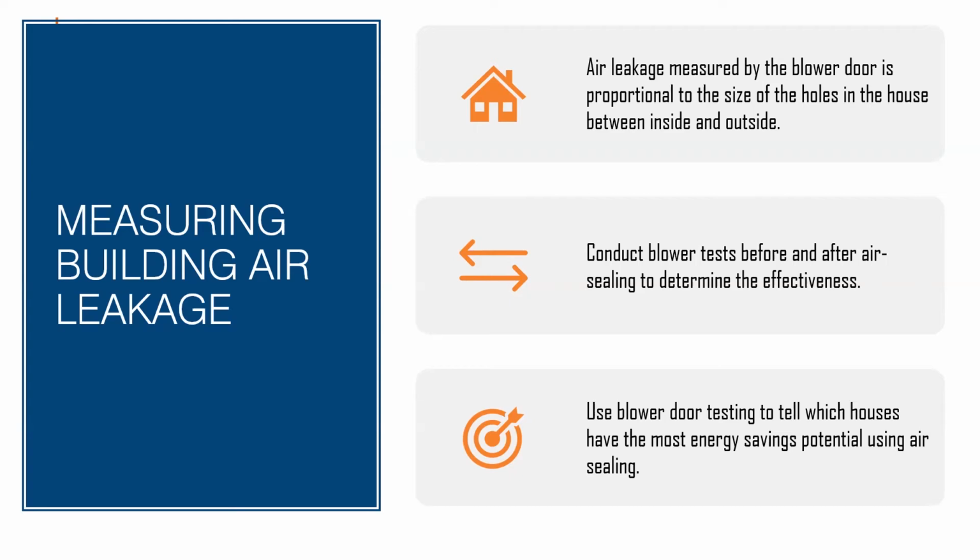Conducting blower door tests before and after air sealing helps determine the effectiveness of our work. Post-testing can also reveal whether any big leaks were missed. And the rule of thumb at the top is that the blower door test result can be roughly compared to the total size of a hole in that home, as though you could add up all the little holes and communicate that size as one large hole.